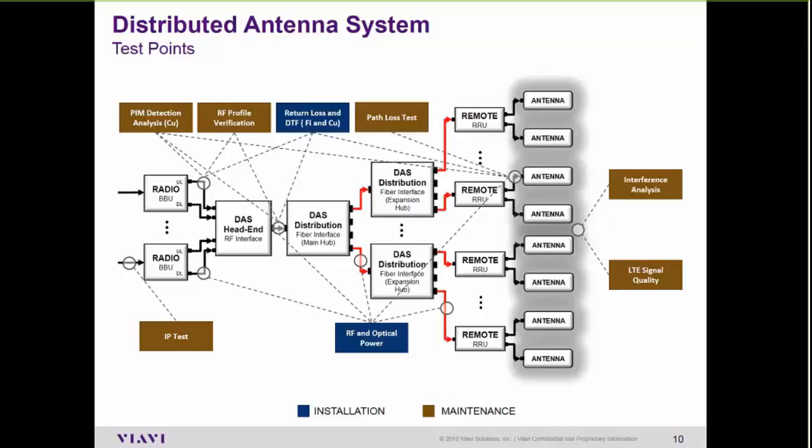Again, you can run the test set remotely, so you can stay at the bottom and a tower technician or a tower climber can take it up on top and connect it in for you, so you can make these types of measurements. But it's a very expensive proposition. So the primary place you're probably going to use a directional power meter today is going to be in a distributed antenna system, say in a stadium or an arena, a place where you can get to the radio room itself and connect directly to the output of the remote radios.